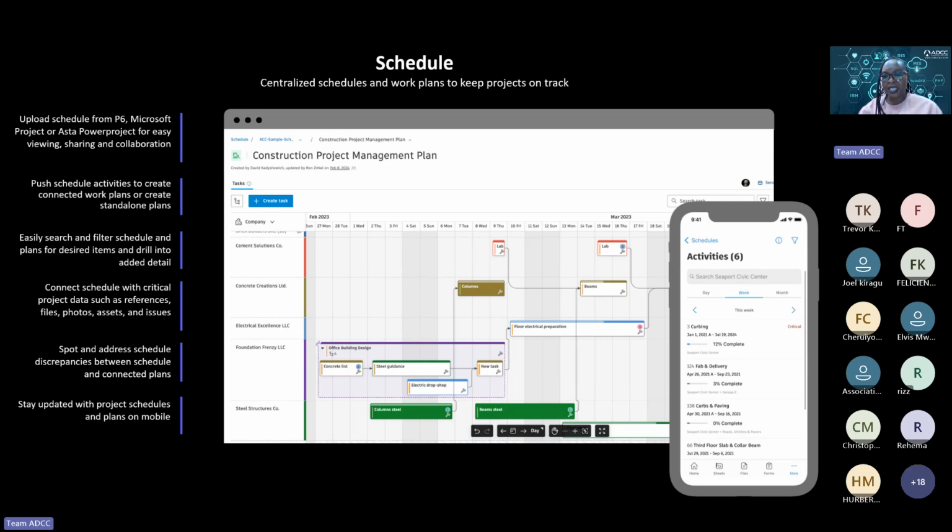So this breaking down of the smaller activities can be done. You don't have to do that from the get-go. Once you kickstart your construction meetings, you can probably have the 2-week look ahead or 3-week, depending on how your project process is. And then during those meetings, that's when you break down these activities and even have them all the way to as many weeks ahead as you would like.